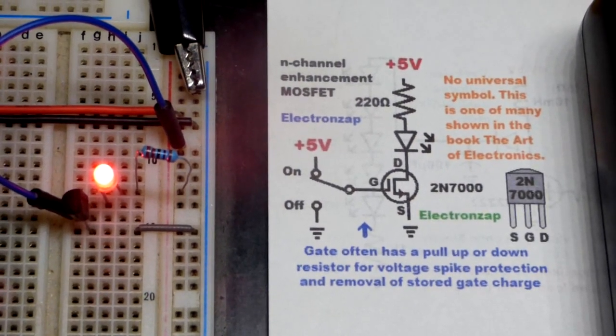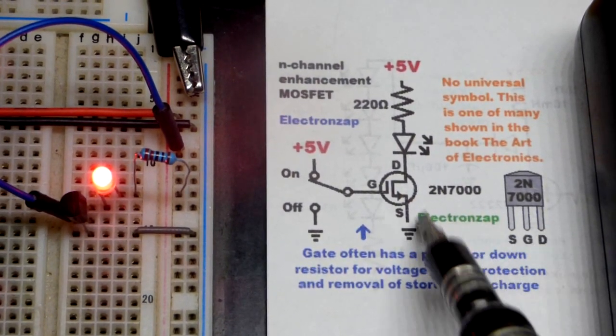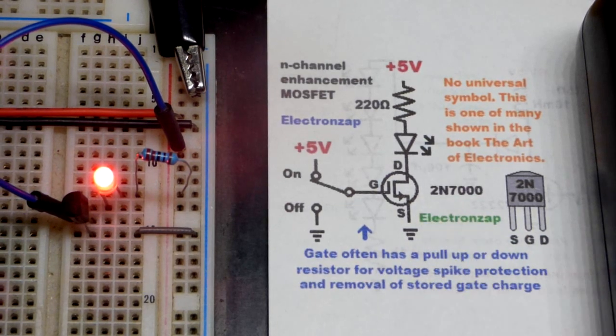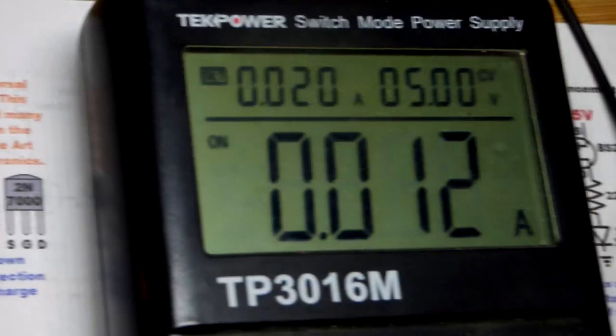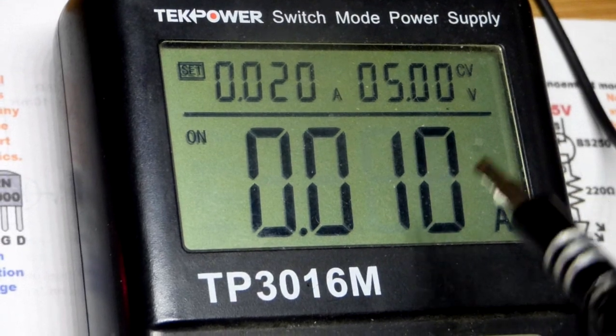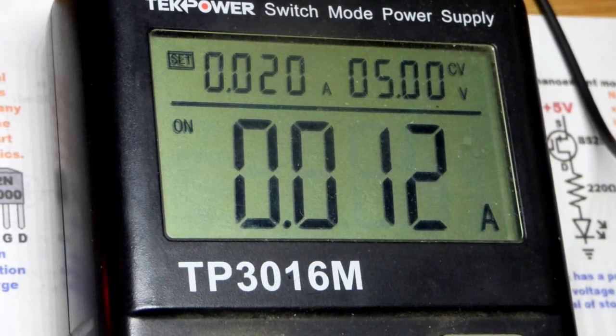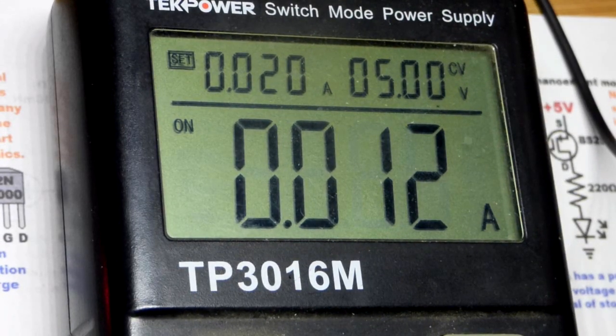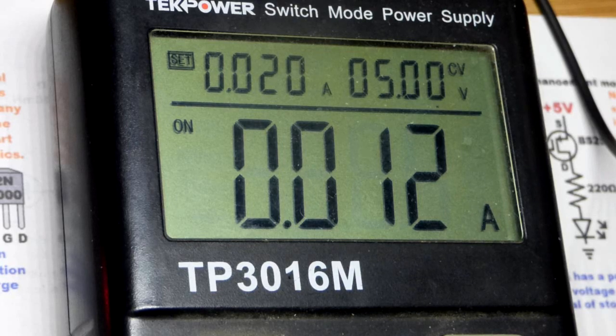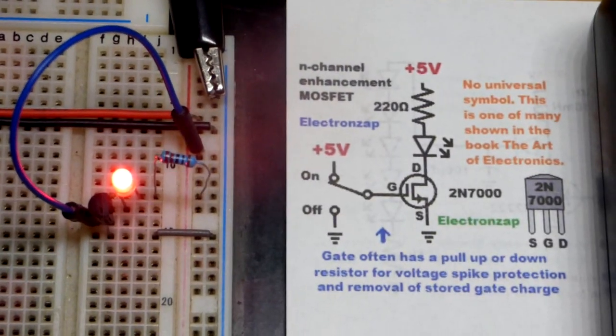But yeah, it's pretty straightforward. These MOSFETs have a little bit of resistance while they are on. They don't conduct probably as good as a bipolar junction transistor. I don't know why that just dropped to 10. That's weird. Okay, we got 12. And I probably kind of lost the connection a little bit somewhere. So, in any case, we got about 12 milliamps of current flowing. I think we'd have a little bit more with the bipolar junction transistor.